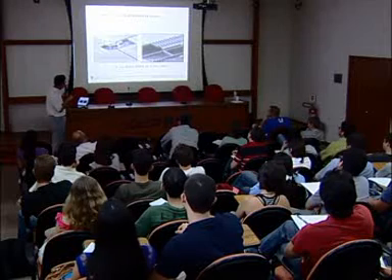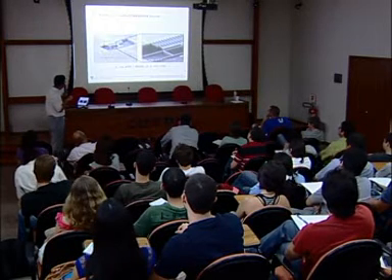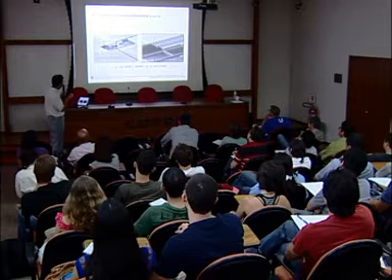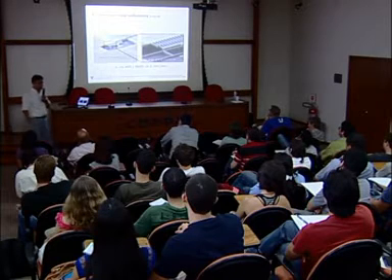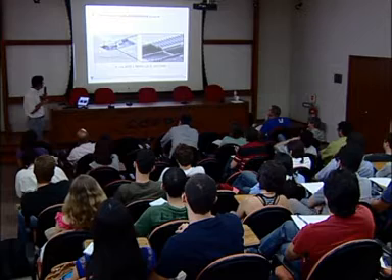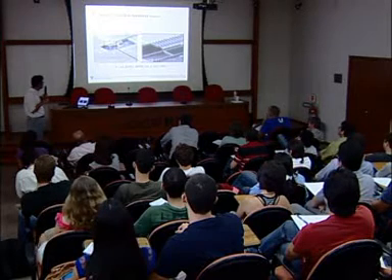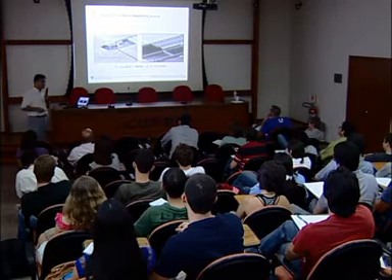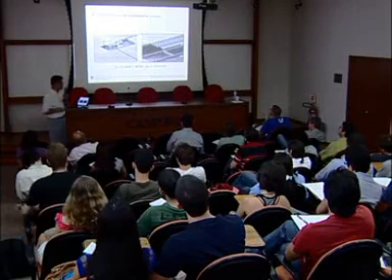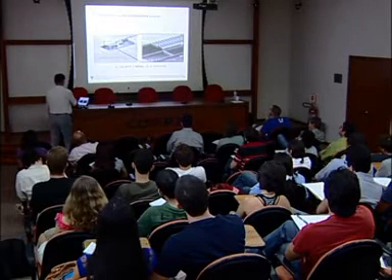And when we apply electric potential to this structure and this structure, this cantilever beam will be attracted to this side. Okay? And then if we remove the potential in between, it will return to the original position by elastic energy. Okay? So this is a zoomed-in view of those comb drive structures.